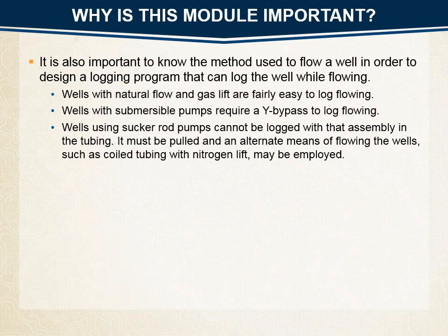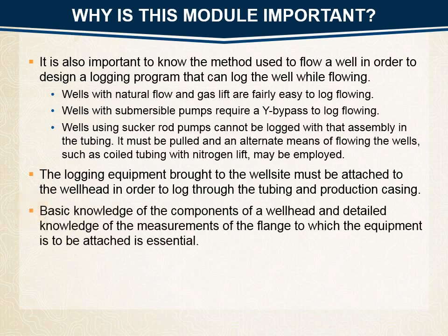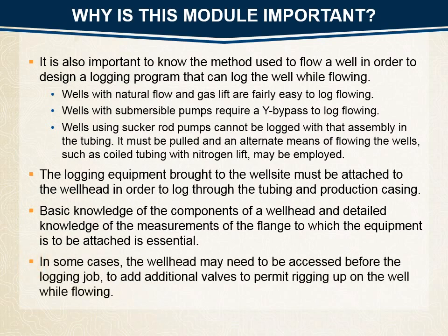be employed. The logging equipment brought to the well site must be attached to the wellhead in order to log through the tubing and production casing. Basic knowledge of the components of a wellhead and detailed knowledge of the measurements of the flange to which the equipment is to be attached is essential. In some cases, the wellhead may need to be accessed before the logging job to add additional valves to permit rigging up on the well while flowing.